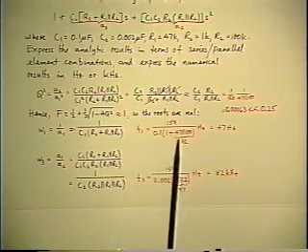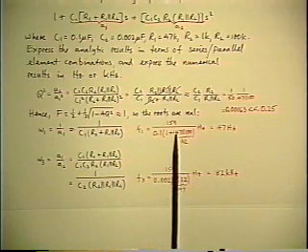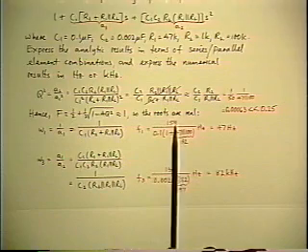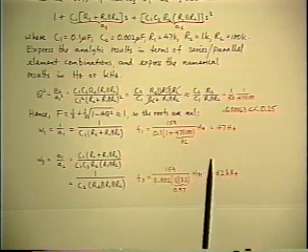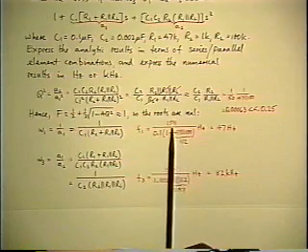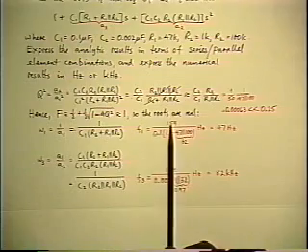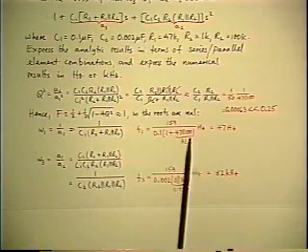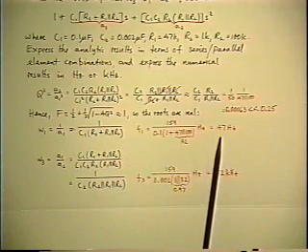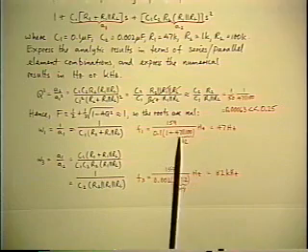So when you substitute numbers, you've got a 1 over 2 pi, and it's convenient to remember that 1,000 over 2 pi is 159. Saves you one keystroke. And 160 is usually good enough anyway. And if you have the capacitance in microfarads and the resistance in K, this gives you the result in hertz with 159 in the numerator.